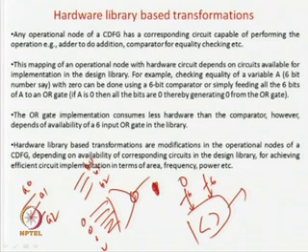If all the XOR values are 0, that is, all the bits are individually equivalent, then only is the answer equivalent. So a comparator will actually involve XORing all the input bits, which you have already learned in the digital design undergraduate course. A general 6-bit comparator requires 6 XOR gates to do that.